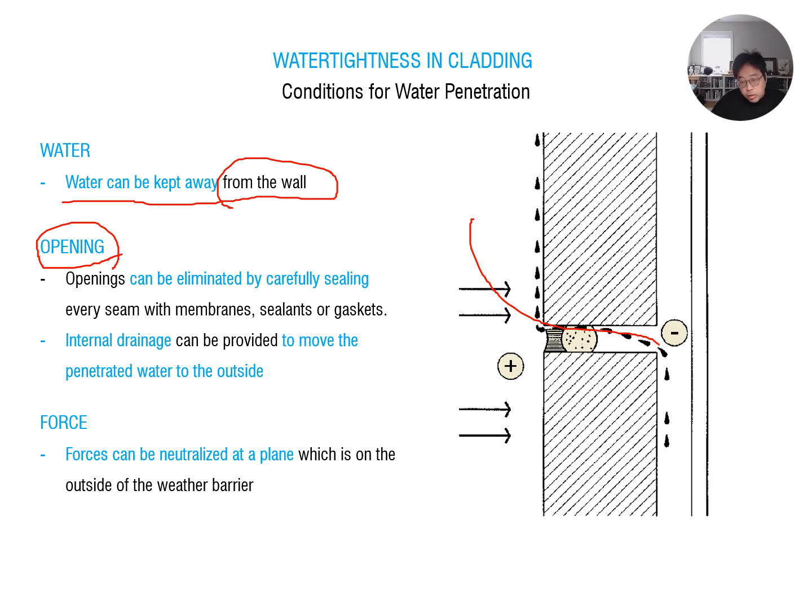So we can say water is coming to here, right? This is the exterior, the fiberglass mesh sheeting. Of course, you can protect against the water, but when water just comes in, it has to drop down right away. To protect against the forces, we need a proper weather barrier over the sheeting. We have to provide a waterproofing membrane here, and also provide cavity space, which is ventilating air, to dry out this water as much as possible. Okay, so let's look at the possible force types on your building and show how we can protect against water from the exterior side.